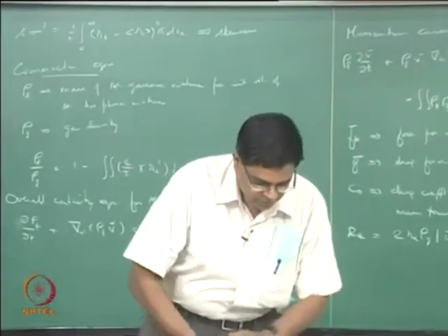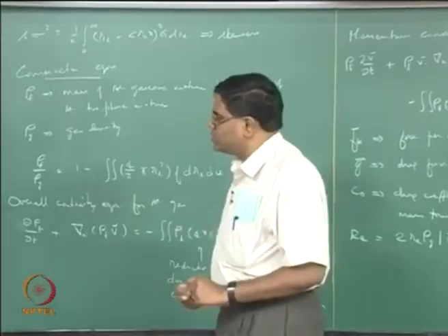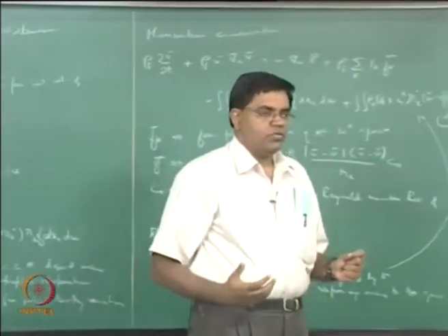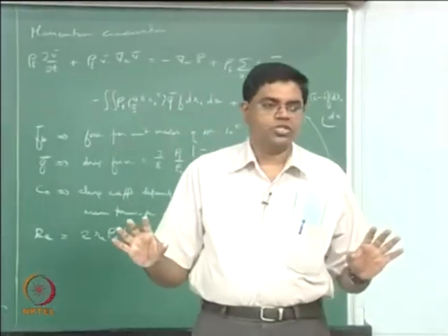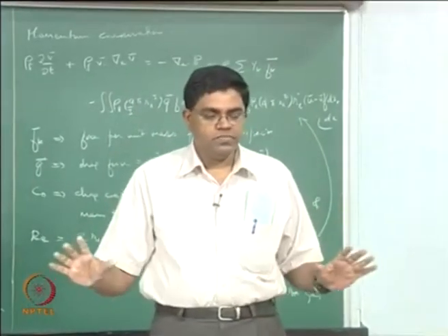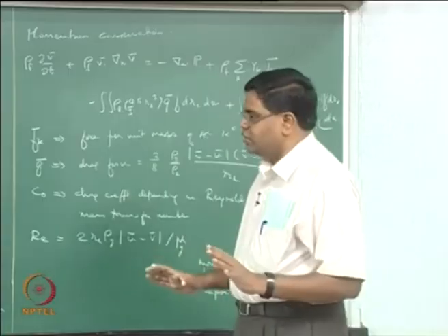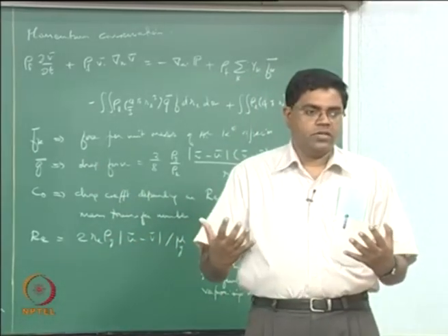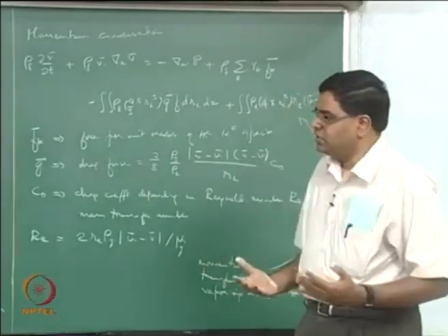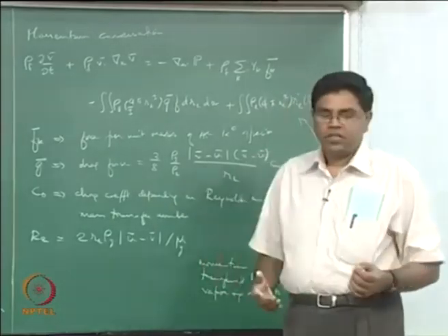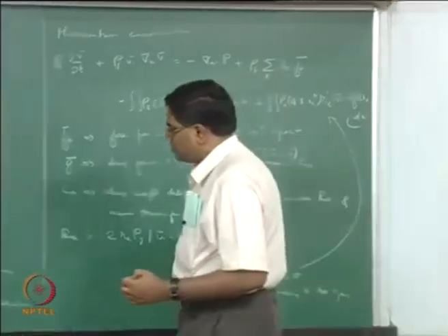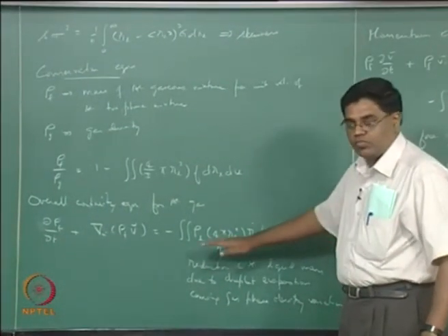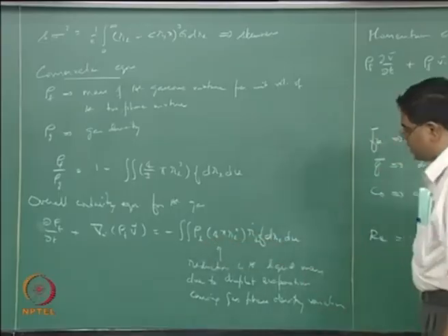So what then happens is, if you now write out these equations, this is sort of similar to the governing equations that we wrote for a homogeneous combustion, that means all species being gaseous, but here this is for heterogeneous combustion, where you are now throwing in a bunch of liquid droplets, typically fuel droplets, and in each of these equations you can see that there is a source term that is coming out, at least one or two source terms that are coming up because of the droplet.